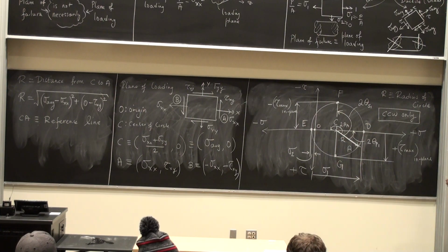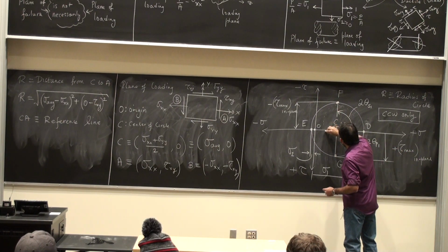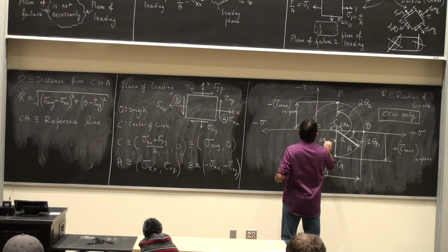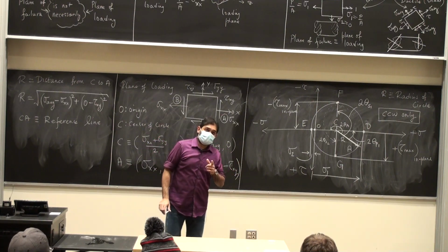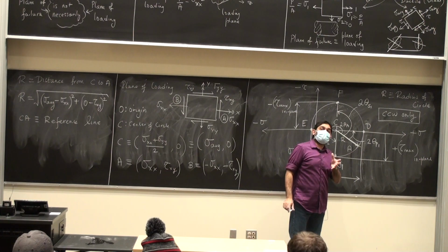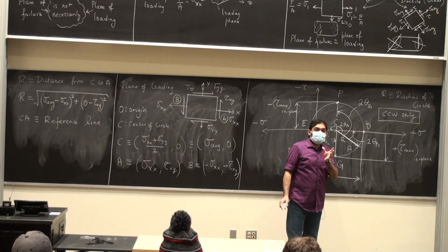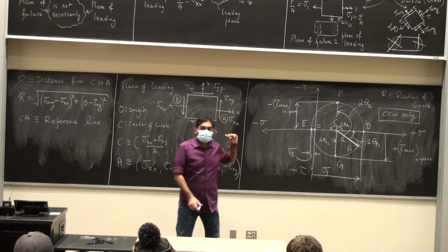And if you want 2 theta S2, you go all the way from this line to theta S2. Remember, counterclockwise. Don't go clockwise. If you go clockwise, you have to draw the rotation. You can go clockwise, but you have to draw the orientation properly. So it is wiser to go counterclockwise when we follow all the sign conventions.